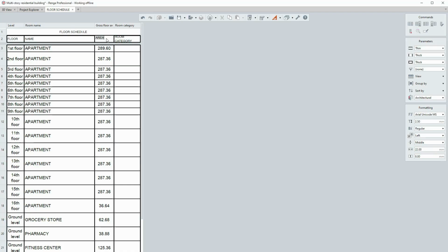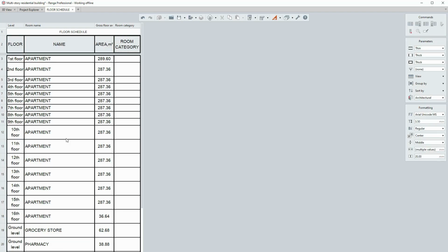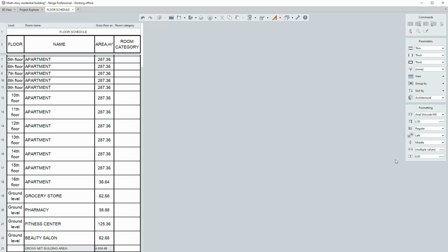To insert a symbol into a schedule or column header, move the cursor to the input field. Right-click the field to open the shortcut menu and select the symbol option. Select the symbol. If you format the header or total row, the format rules are applied to each cell separately. If you format the group header, the format rules are applied to all the group headers. If you format the schedule cell with values, the format rules are applied to the whole column the cell belongs to.